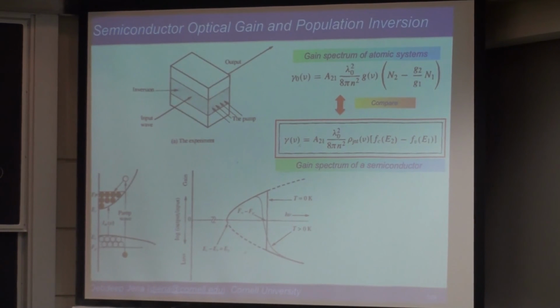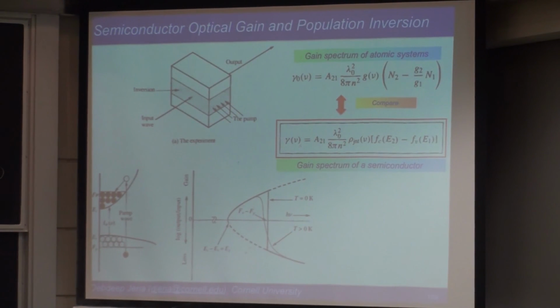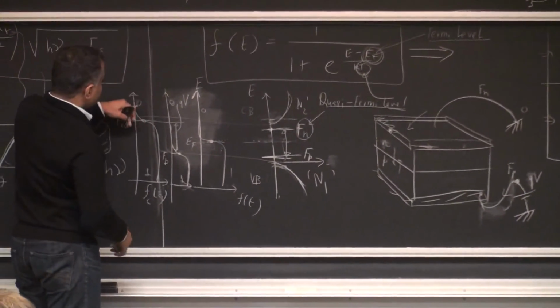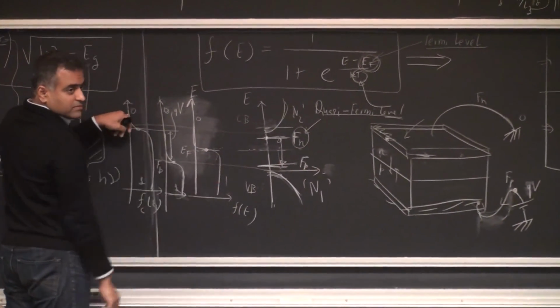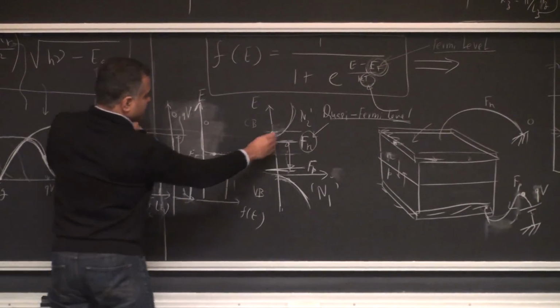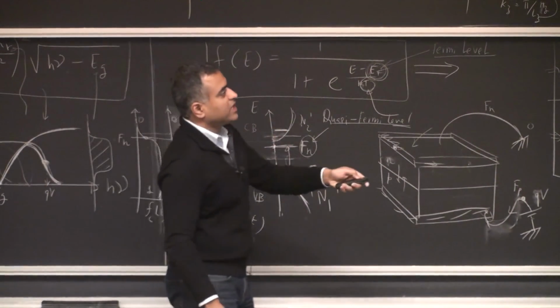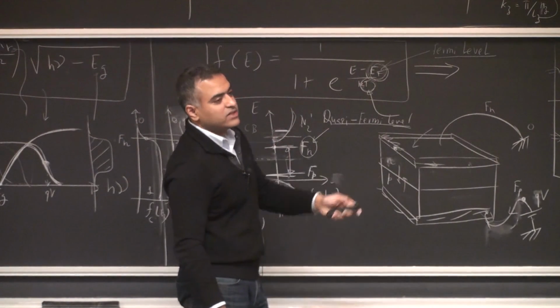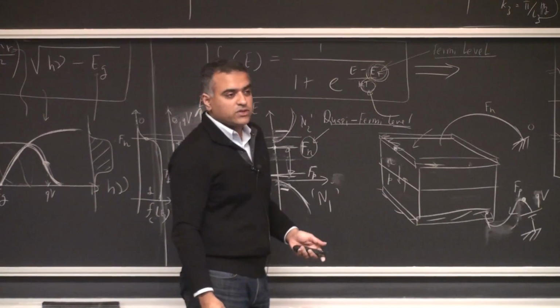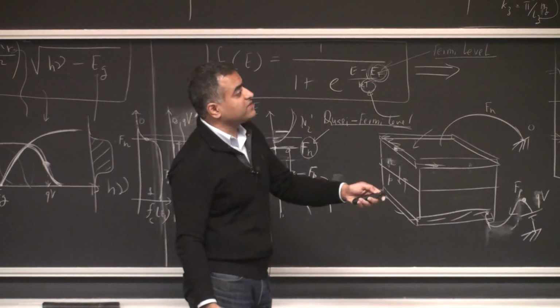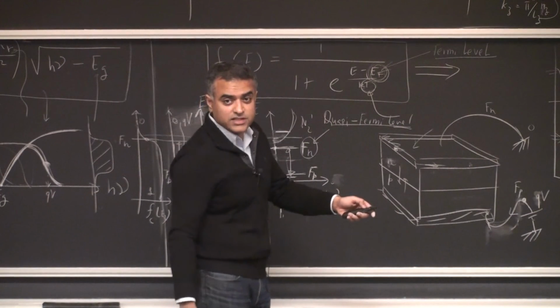In fact, let's say I look at a photon energy larger than the gap, then I'll get basically a 0 minus 1: a state from here E2 minus a state from here E1. So I will get a negative gain coefficient, which is actually the absorption coefficient of the semiconductor. This factor is minus 1, so the whole stuff sitting in front is still the absorption coefficient of the semiconductor.